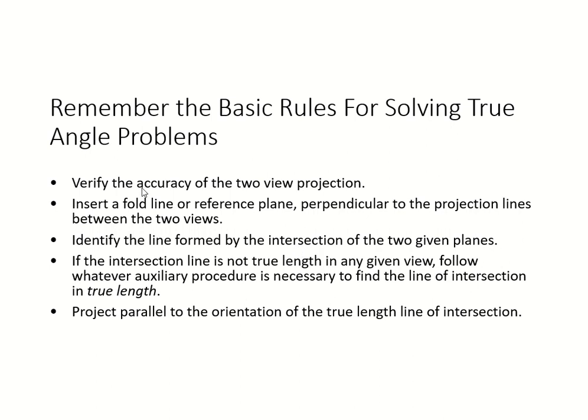Your fold line is your reference plane, in other words, and it has to be perpendicular to the projection lines between the two views. You will always have two views, and you throw the projection lines in between them all the time. So you should get it by now. We are now already on chapter 2.